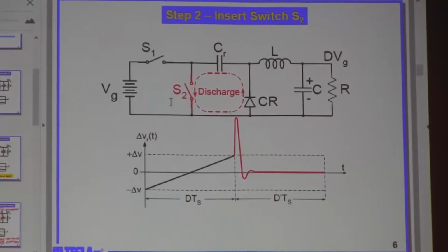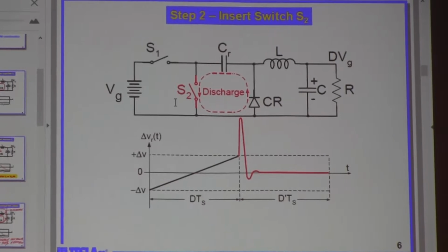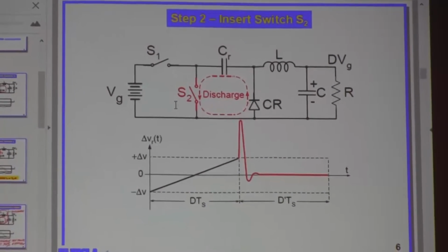Okay, but this won't work because, why? Because when I discharge it, it's going to be a chaotic discharge. Because in this loop, you know when you short a capacitance, what happens? You have 100 volts on it, you short the capacitance, have you seen it? Then there is all kinds of current because the capacitor says, I want to be discharged. Give me the shortest possible time. You know, physics, right? But we can prevent that discharge, which is of course bad because when you multiply with the frequency, this is all the losses.